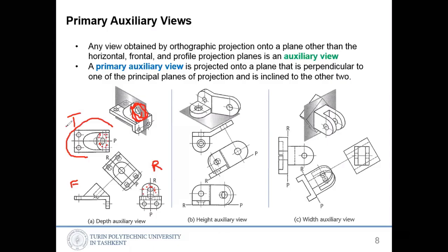So with these three views, first, second, and third, we cannot see it. So what we do is make an auxiliary view here. We make a line parallel to this side, and then bring every piece of information from the three views. We measure and generate this view.